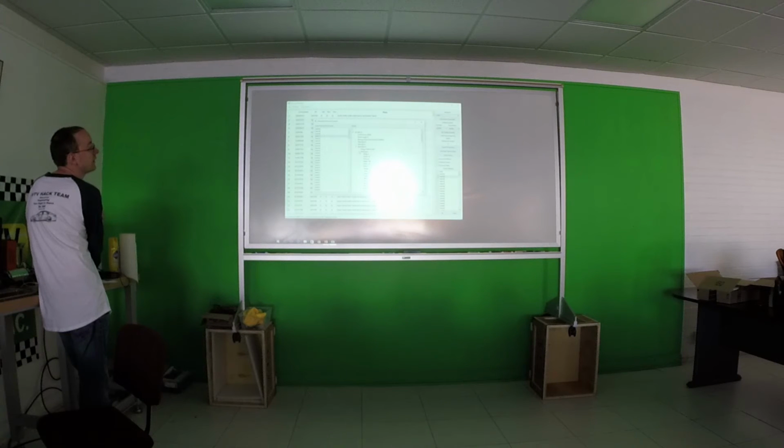If you click the histogram here, you'll see which values were found and how often. The values are in both decimal and hex. So I can see a value of 7A was seen in this byte 129 times. Value 51 was seen only 18 times. So we can kind of use that to get an idea of what these bytes are doing.